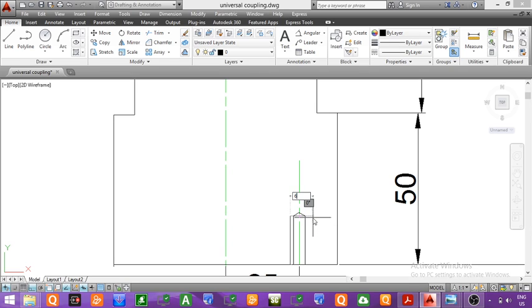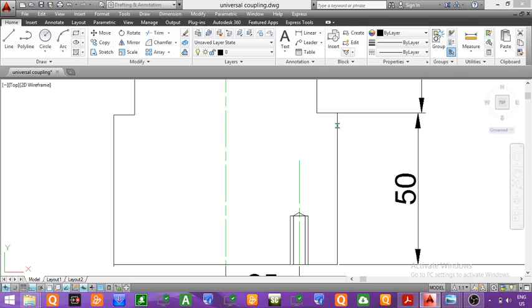and the major diameter is again equal to 6 mm, and again the height will be equal to 16 mm. So you can see here these two lines, inside two lines represent the minor diameter of the thread, the outside two lines will represent the major diameter of the thread. Now the major diameter of the thread will be equal to 6 mm.